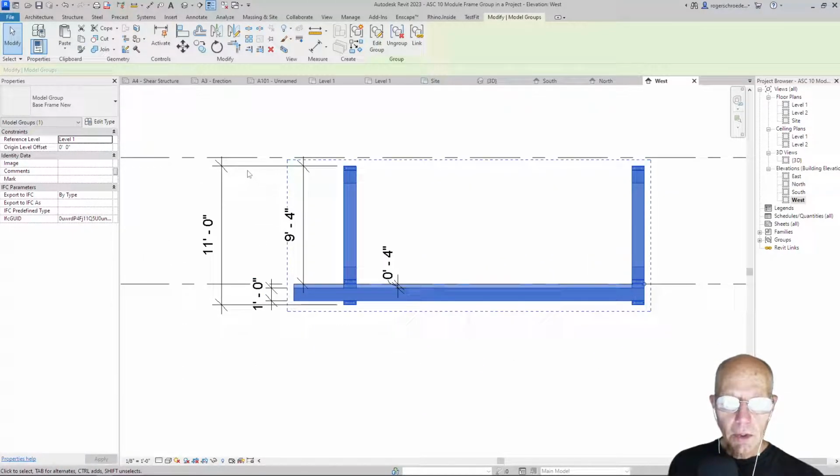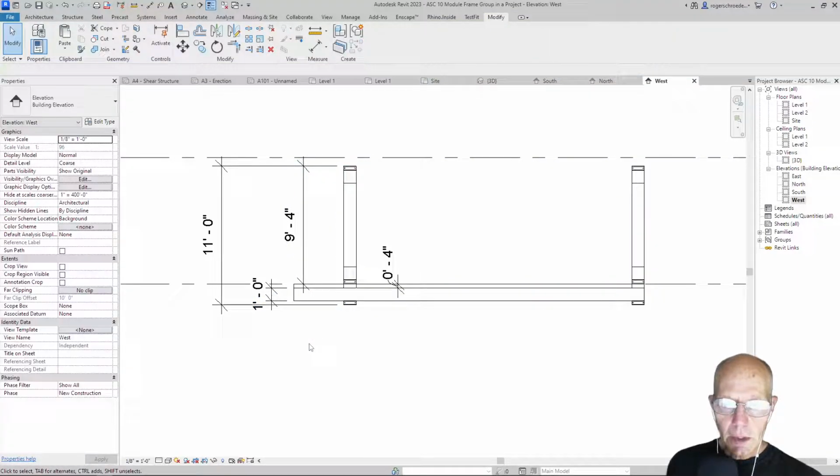The overall height of the unit is 11 feet. Once again, thinking about being shipped to site, that creates a workable envelope from the base floor up to the very top connector, which might be the next module with its ceiling unit on it, of 9 feet 4 inches of headroom. You can see I've dimensioned the 4 inches. That is the mass timber slab. Imagine 2x4s turned on their side and spanning 8 feet. The bottom beams that go across are 1 foot thick. And I think that pretty well covers all the dimensions on an assembly.